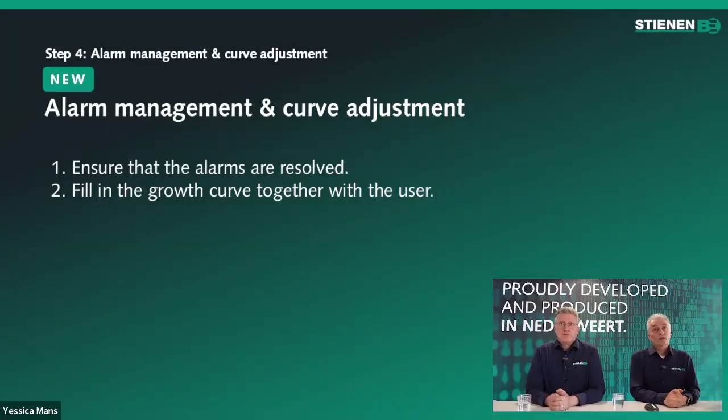Finally, ensure that all alarms have been resolved. You can see which alarms are still active in alarm management. Then fill in the grow curve together with the end user. If you don't have any data available, determine the number of breakpoints together with the end user.